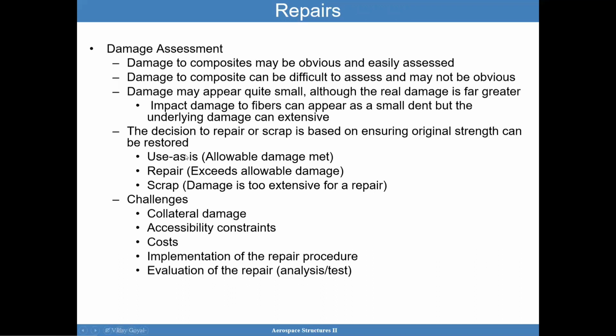And so use as is when the allowable damage is met. Repair is when you exceed the allowable damage, and scrap is when the damage is too extensive for a repair. Challenges can occur, so you have collateral damage, accessibility constraints, cost, implementation of that repair procedure, and evaluation of the repair can be quite difficult. And it requires analysis and test. And these are not very easy things to address always, especially when you have damage.